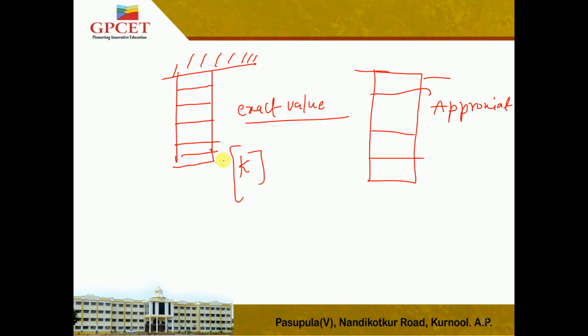the stiffness matrix will increase. Let us say how many parts there are: 1 2 3 4 5 6. In this example, a 6 by 6 matrix will come. With 4 parts, a 4 by 4 matrix will come. 6 by 6 is a very huge matrix, so it takes a lot of time for the computer to solve this kind of problem. But we will get the exact value, that is a different thing. But as far as time is concerned, it takes more execution time. The mesh is nothing but dividing into parts.